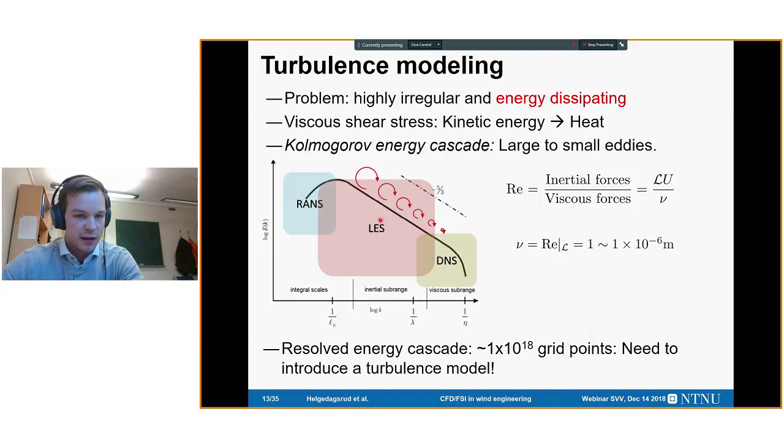The next one is the large eddy simulation. Here you actually simulate the turbulent structures, but you make sure to dissipate the energy before the fluctuations vanish out of your resolved scales. You also have the direct numerical simulation that actually resolves everything, and it's not relevant for industrial applications, but you have a series of benchmark problems where you have DNS results.